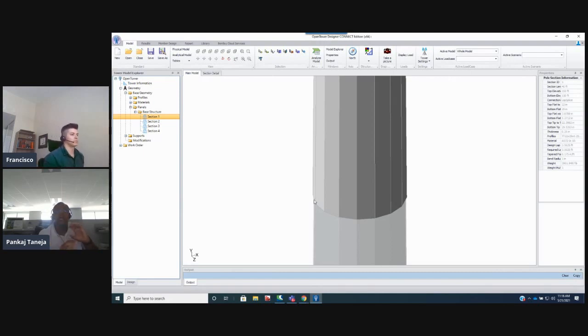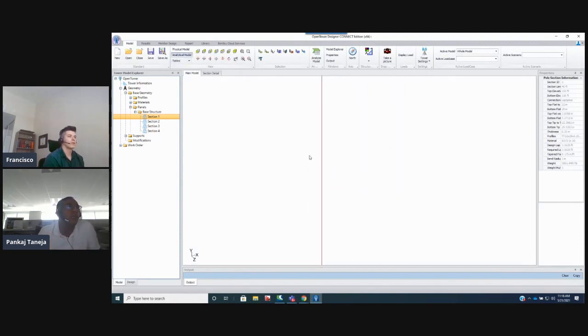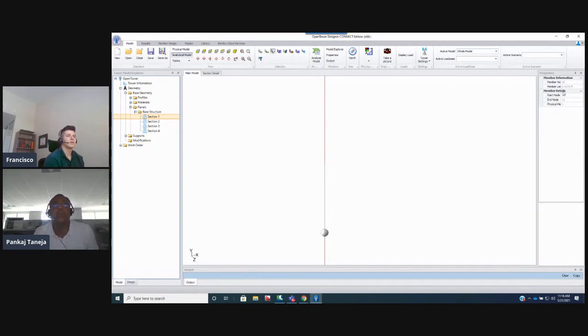And we break these towers into small analytical members. Let me show very quickly on that part. If I look at this and select analytical member, do you see how small the section is? It's only 0.4375 feet that we're talking about, the section where it has the combined section properties.